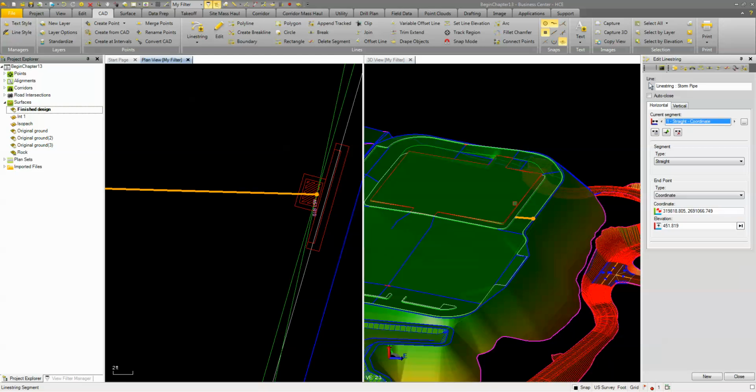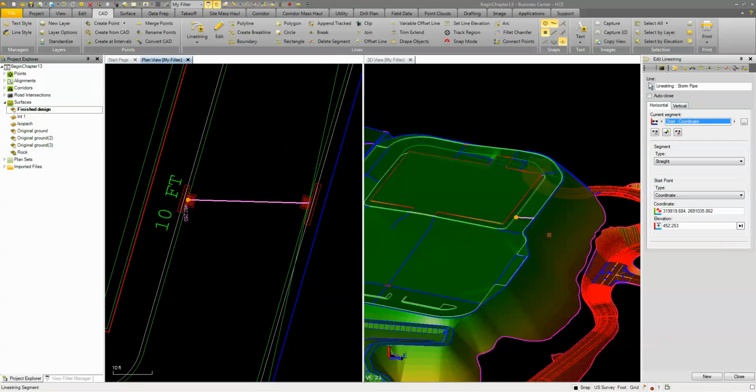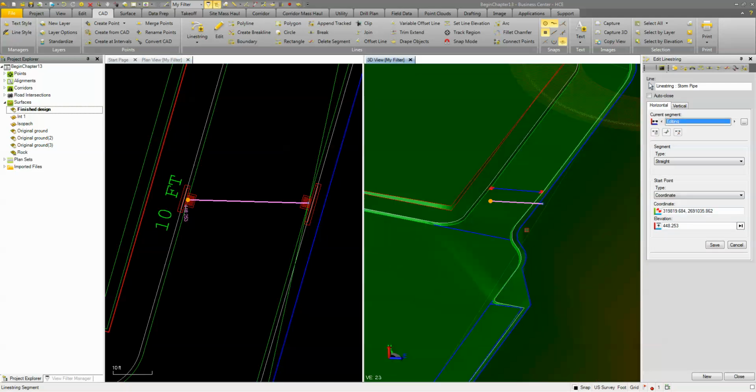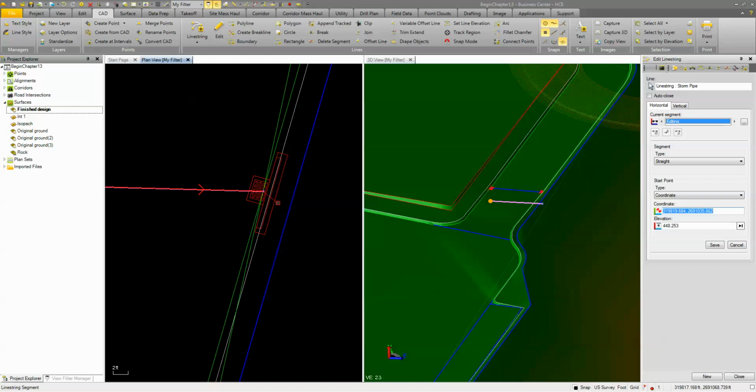So again, we're going to cancel, and for the elevation here, I'm going to hit remove that, and then this one over here, I'm actually going to come in, and again we have a minimum starting point of 4 feet. So we'll hit save tab and save on that. That drops that one down, and then I can come over to this point.